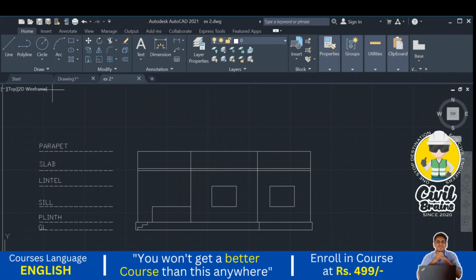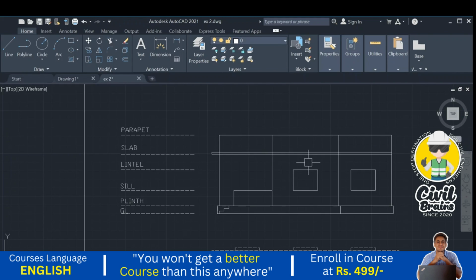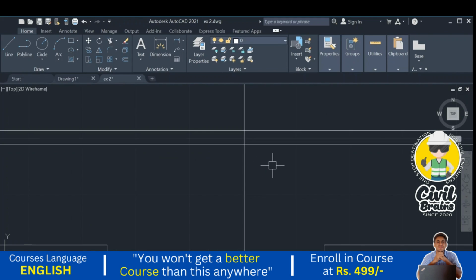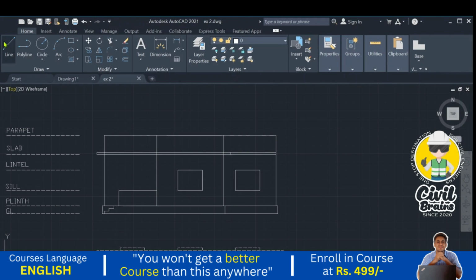Okay, so we'll draw the slab projection 0.45. Press enter. Thickness is 0.125. Press enter. 0.45. Enter. And here also it will be visible 0.45. Only this line we need to show. That's it.